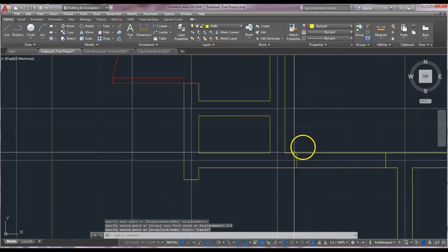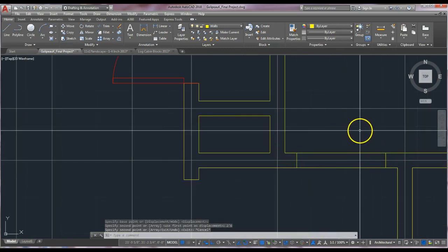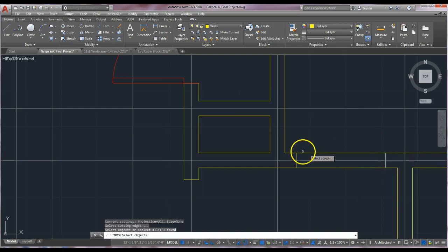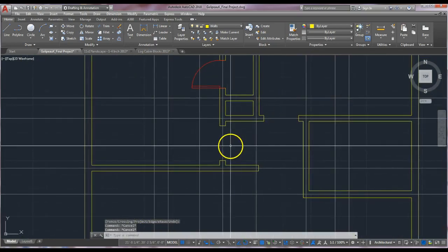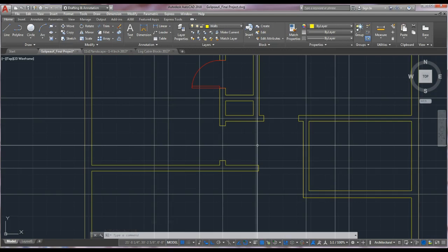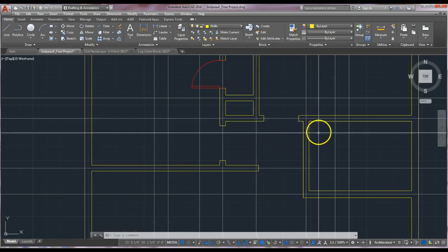We've created another area where our door opening is going to go, and now we can trim. Select the 2 lines and trim away the door opening. So we've got our 2 door openings. It looks like we have a third door that's 2'6", and that's at the bathroom.